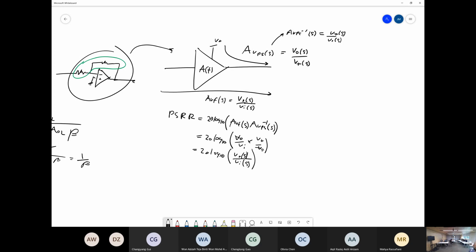What sort of question might we get? Would we have to calculate PSRR? Yeah, you might be given a graph of PSRR. The thing about these quizzes is that they're so ad hoc and arbitrary. You might be asked to get the general trend of PSRR, or to calculate the specific value, or work backwards. If you have a noisy supply and a PSRR of, say, 70 dB, calculate the output ripple. And it's just using this formula.